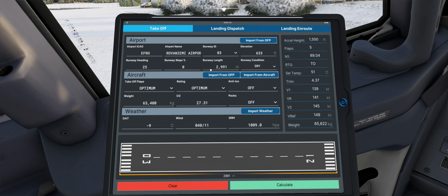So that's what I'm missing here, because you can be limited within your takeoff mass. You can be limited by obstacle limited weight, climb limited weight, or field limit takeoff weight. There is brake energy as well, but I have never used it in real life. So if you are limited, for example, with obstacle and climb limited weight, you are performing the improved climb, and again the improved climb is missing here. So this acceleration height 1500 is just for your eyes here.